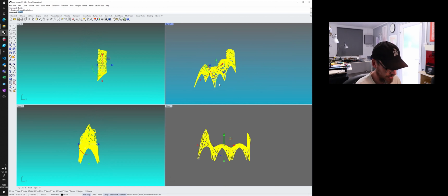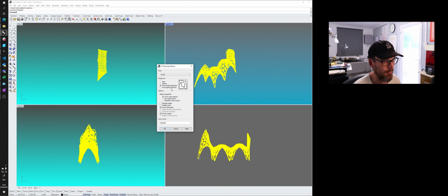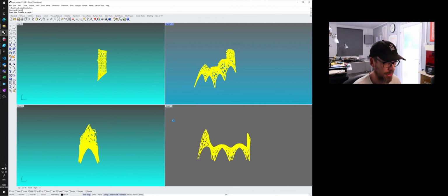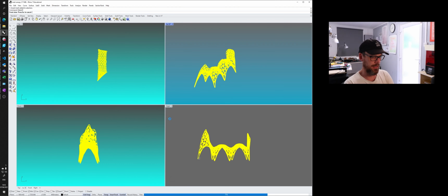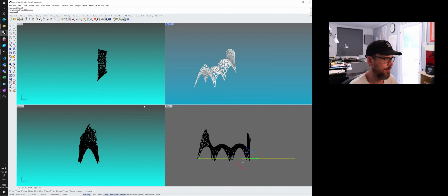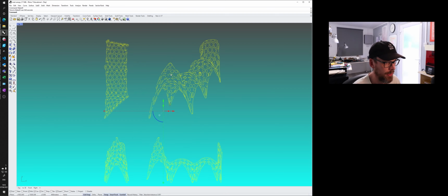Got it, so it's make 2D, third angle. I'll remove hidden lines for this object. Scene silhouette sounds good, and I'll make sure it's grouped. This can take a few moments per viewport. Cool. And there we go. So if I maximize that.